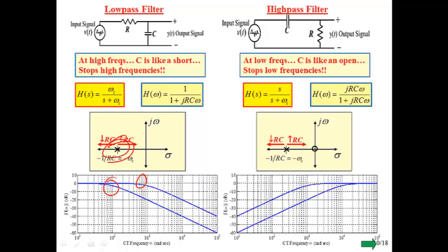And again, just summarizing the results that we've seen and recognizing the effect of changes in RC time constants. So notice, let's talk about the low pass case. We're used to, for this circuit, the RC time constant, if it's small, we say that it can respond rapidly to transients. Well, when it's small, the pole has moved further out, and when the pole has moved further out, our cutoff frequency is even further out.